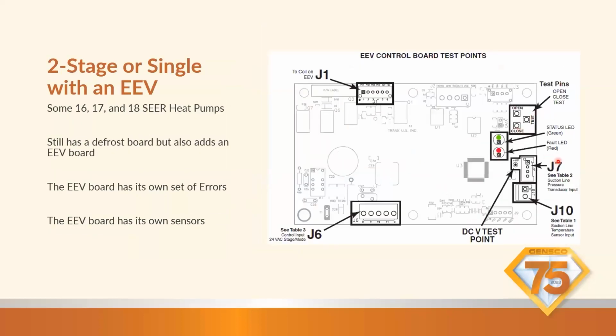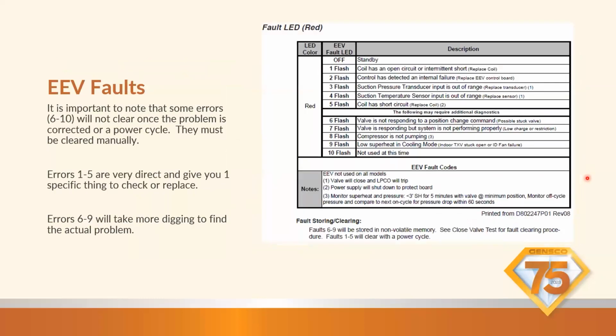Test to close for 10 seconds. It'll wipe the memory of these faults and they'll go away. Now, if they're still having the same symptom after it's run, they could come back. So, depending on what the error code is, if it's an 8 flash, they had a bad fuse, great. You know what it was. You fixed it. That should not come back.